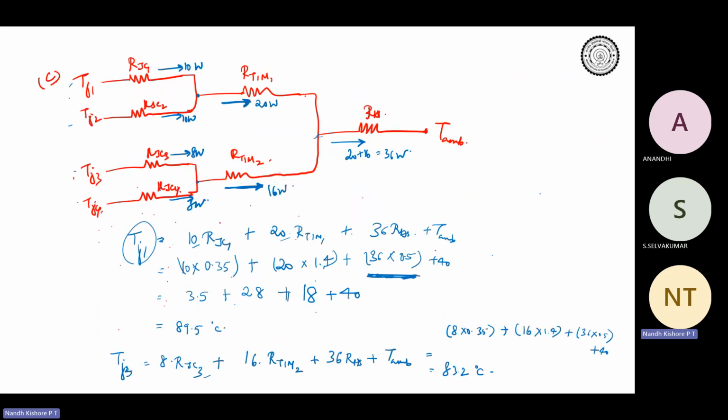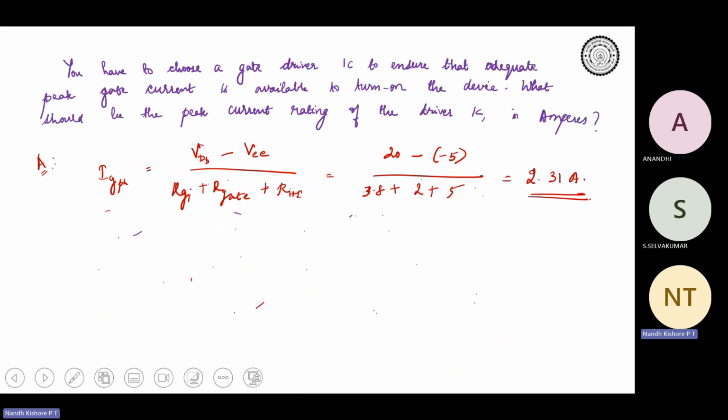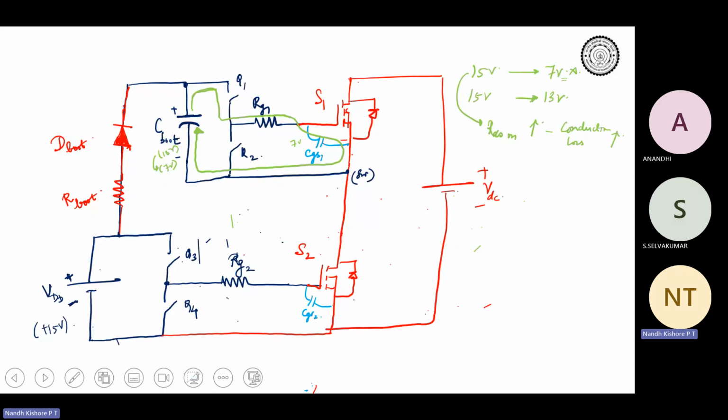That is how you will design your bootstrap capacitance. You don't want the fall to be too much. So if I want to achieve this, what should I do? Should the capacitance be high or low? Capacitance should be high, obviously, right? So that the discharge is very low. Now the point is, if capacitance is high, what about the charging time?